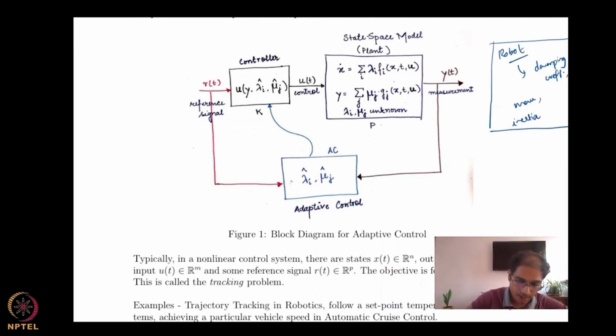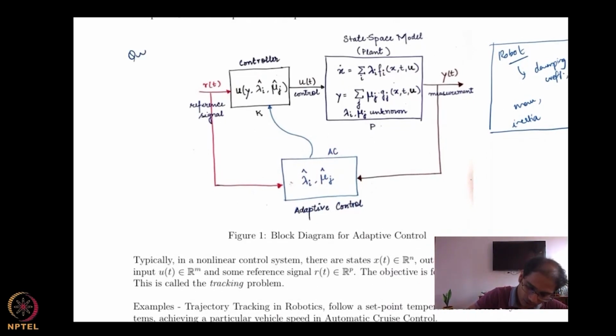If you consider, say, a quadrotor system, you use aerodynamic lift in order to fly the quadrotor. So there are parameters like lift coefficient, drag coefficients, and so on. On top of this, there are inertias and masses that are unknown. So there are many unknowns that are very common in such systems.